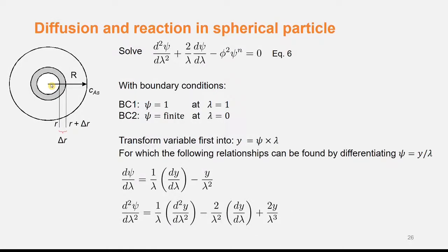In the first part of this lecture, we set up a material balance inside a catalytic pellet in order to understand the effect of reaction and internal diffusion on the reactant concentration and overall rate of reaction inside the catalyst pellet. The material balance resulted in a second order differential equation for the concentration of reactant A as a function of radial position in the pellet.